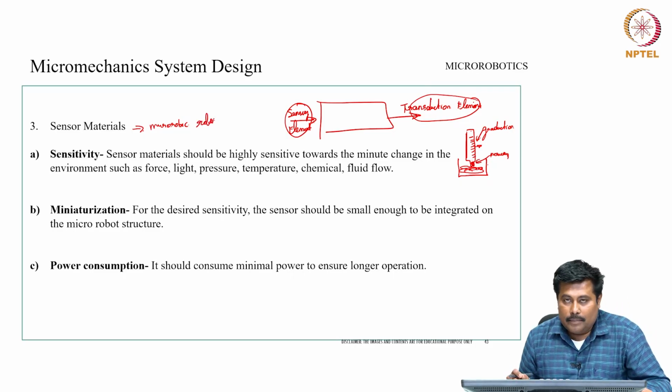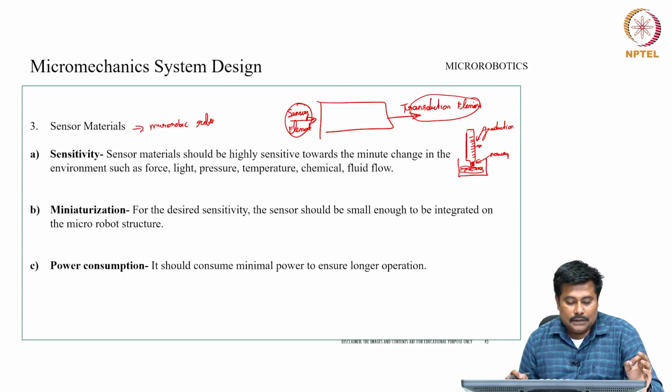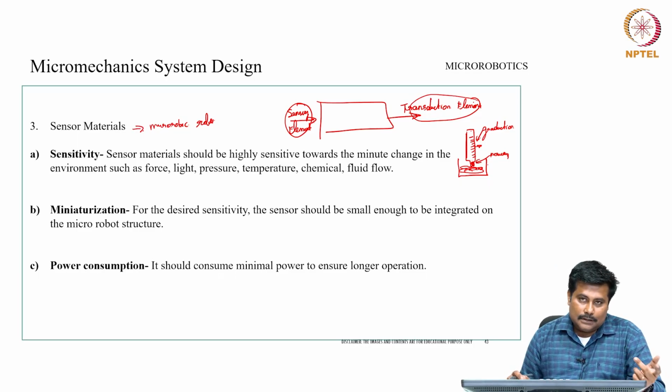So, these sensor materials should have high sensitivity towards minute changes in the environment, such as force, high pressure, temperature, chemical and fluid flow. From a miniaturization point of view, for the desired sensitivity, the sensor should be small enough to be integrated on the micro robotic structure.